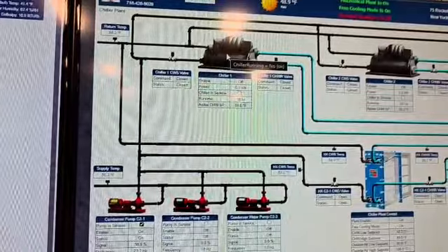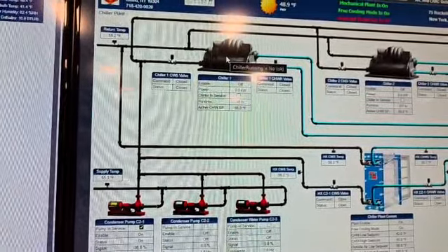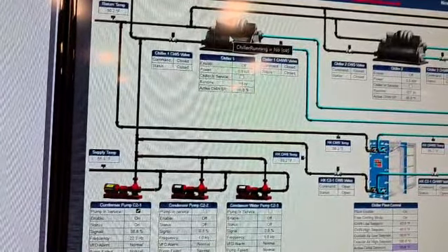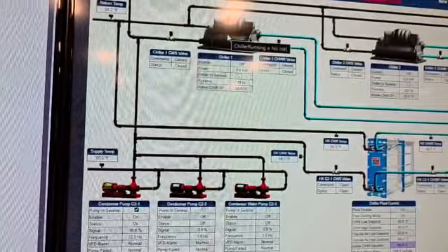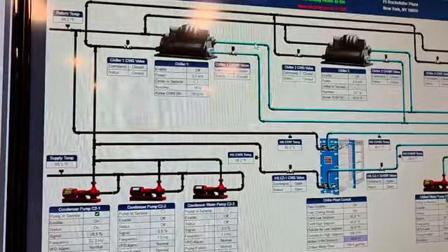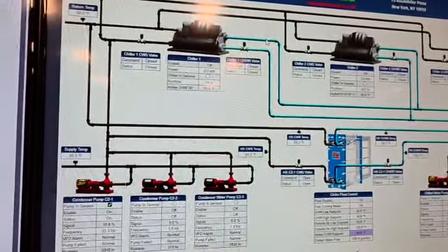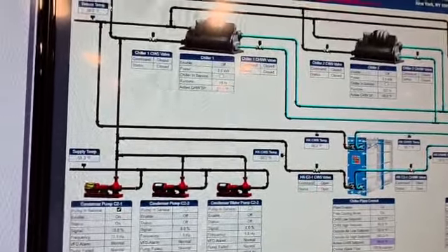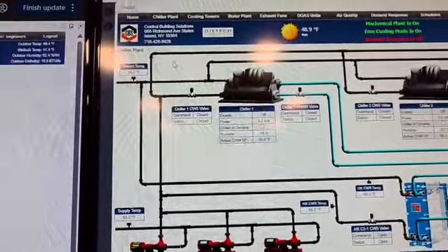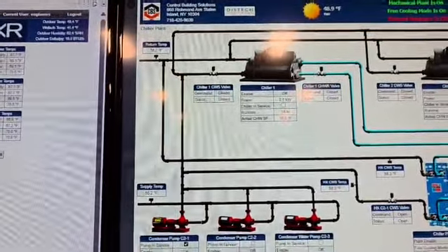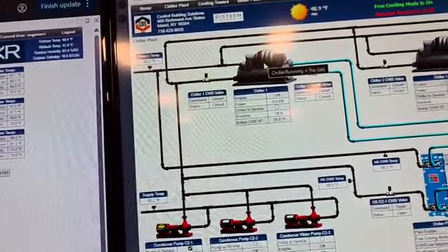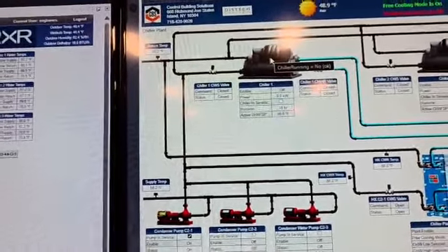So you need to keep that temperature low so the compressor can keep working, like a car. You need to cool down the engine with the, what's it called, the radiator. So in this case, the water we're supplying to the compressor needs to be cold so it can cool the compressor down. Yes, right. So the water that you supply to the chiller could be up to 80 degrees, no more. Anything higher, raising the temperature, it won't cool the compressor. Right. I see.